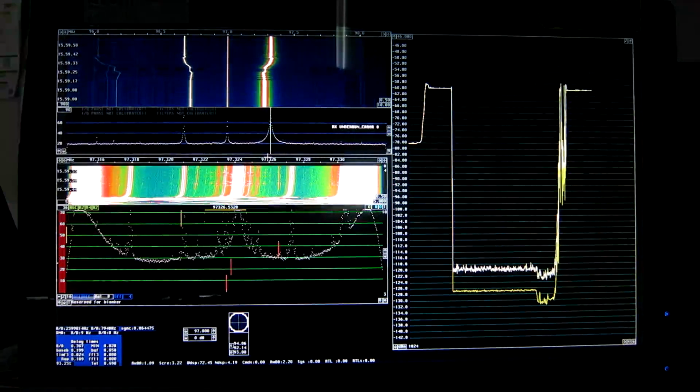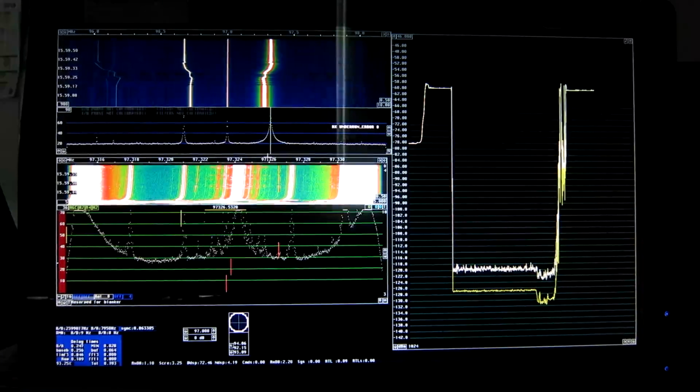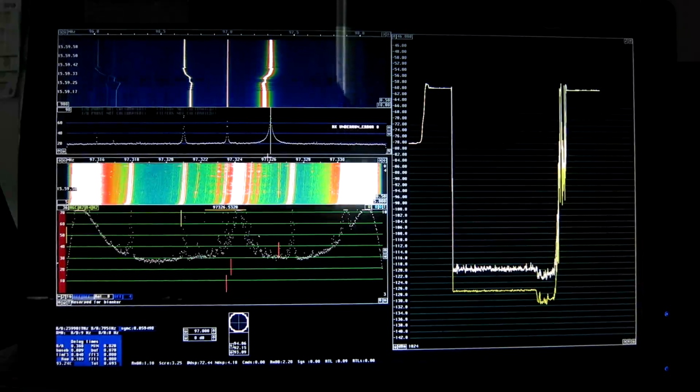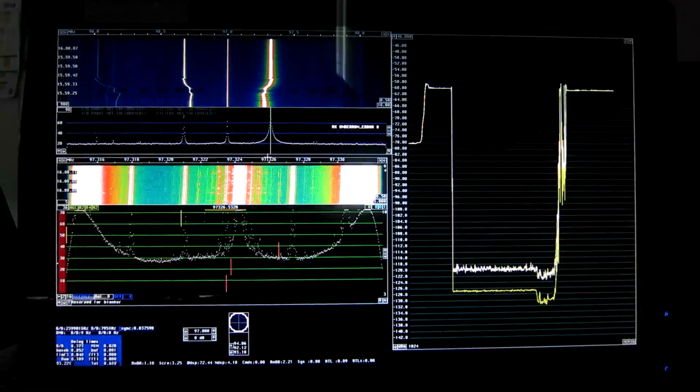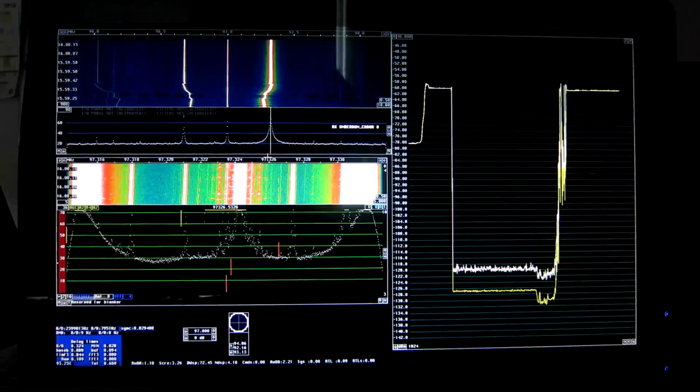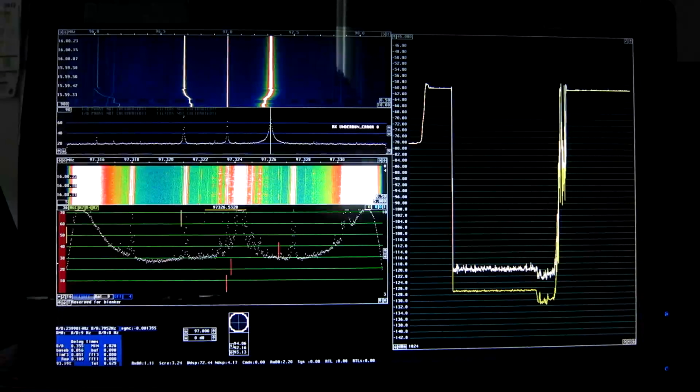It should be quite clear this is not suitable for crowded bands because of the many close-spaced aliasing spurs. They would be suppressed by use of a better window, but then it would not be possible to run at 2.4 megahertz anymore with this dongle.